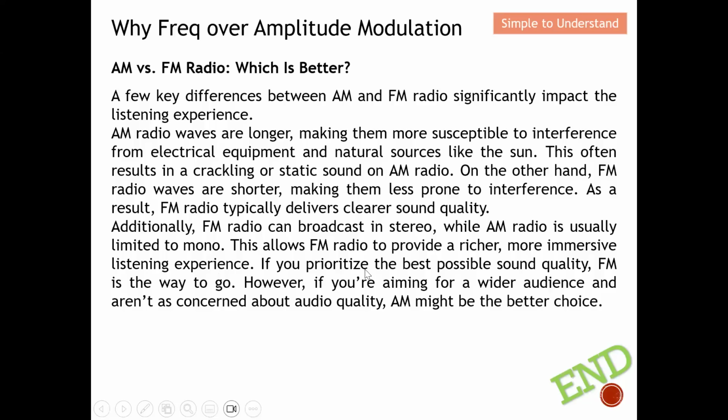So if you prioritize the best possible sound quality, FM is the way to go. However, if you're aiming for a wider audience, which means that you want to send over a longer range and aren't concerned about the quality, then AM might be the better choice. So with this, I'd like to end this discussion. In this discussion, I have explained why frequency modulation dominates as compared to amplitude modulation.